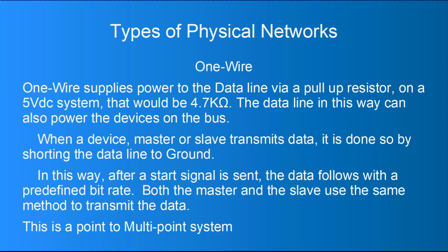Some of you may have already seen these sensors. They typically come with 3 wires coming out of them, a red, yellow and a black from memory. Black being the ground, the yellow being the data wire, and the red can optionally be connected to either 5V supply or left open circuit, not connected to anything.